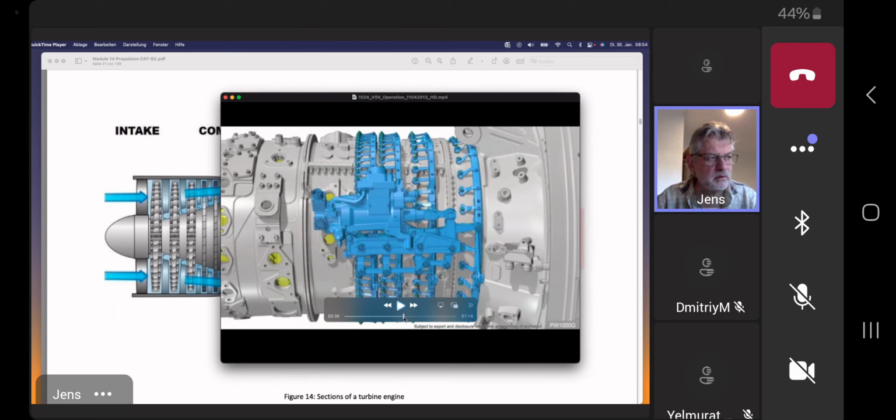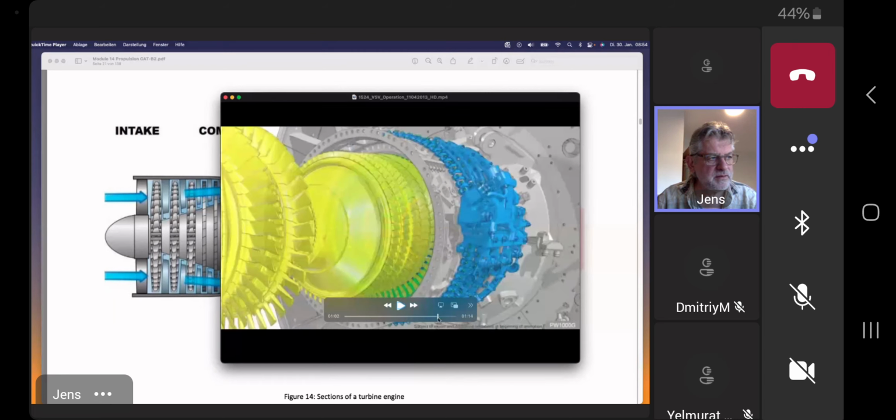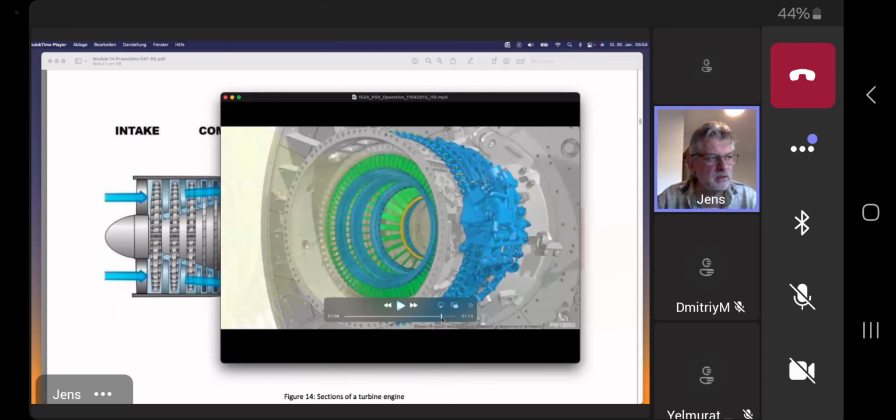I skip a little. You see the actuator is now moving the individual vanes via the link. Let's remove it. So what was the idea? The angle of attack is influenced by two speeds. The first is the speed of the rotation, so my RPM.